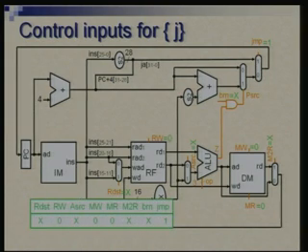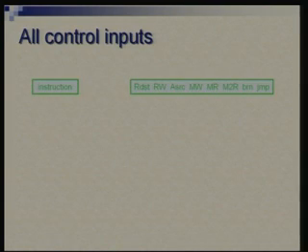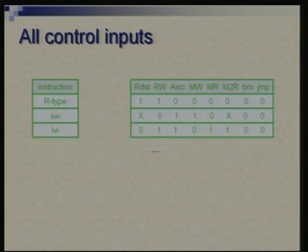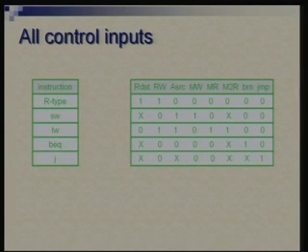This is just a sub table for jump. So we will tabulate the instructions, and against them we will have all the control signals. If we put the opcodes of these instructions, from those opcodes we need to derive these control signals, and these two together will form a compact truth table for the controller circuit. Once a truth table is given, we know how to design a combinational circuit. There are many ways to do it, but I am sure you at least know one.